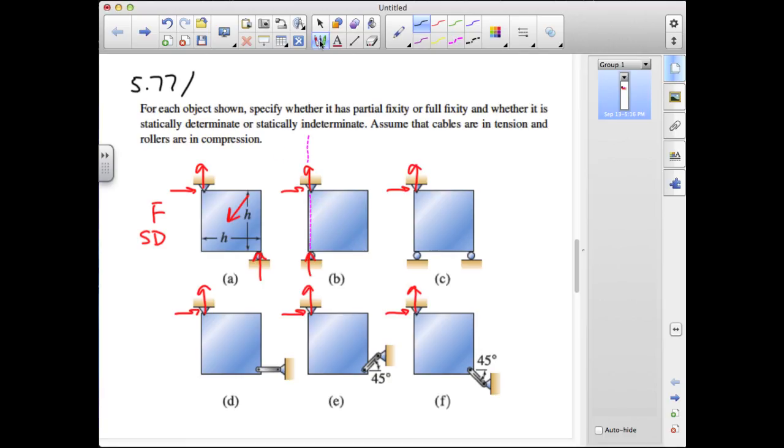But if the external force didn't do that, if it was over here somewhere, we would have rigid body rotation about that pin. As soon as we started to do that, what would happen is that as we tried to make the body undergo that rotation, more of it would be squeezed into the space between those 2 supports, and we would get an increasingly large normal force there at the roller that would cause some binding. So we might have eventually a friction force that develops that would act to oppose that rigid body rotation.